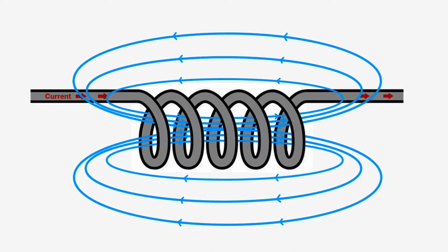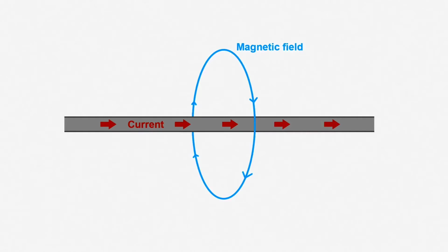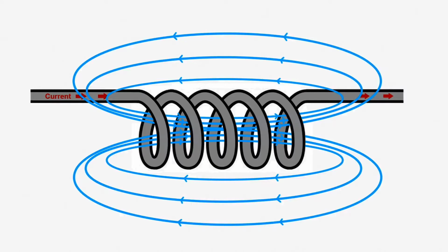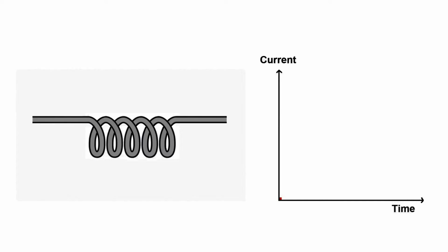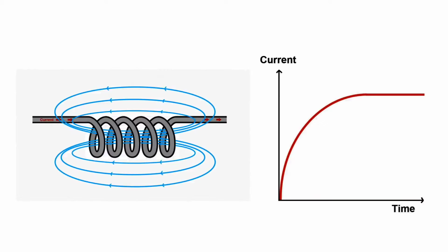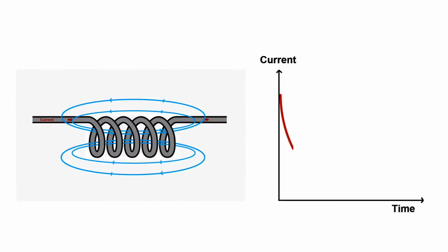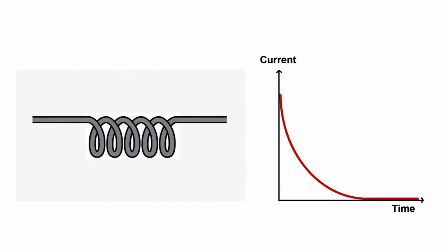Generally speaking, an inductor is a device that temporarily stores energy in the form of a magnetic field. Inductors are usually just coils of wire, and one of the basic properties of electromagnetism is that when you have current flowing through a wire, you'll create a small magnetic field around it. So if you coil up a lot of wire, you'll get a stronger magnetic field. When current first starts to flow through the coil, a magnetic field starts to expand, then stabilizes, and then you've got some energy stored in the magnetic field. When current stops flowing, the magnetic field starts to collapse, and the magnetic energy gets turned back into electrical energy. So they're kind of like a temporary storage area for energy.